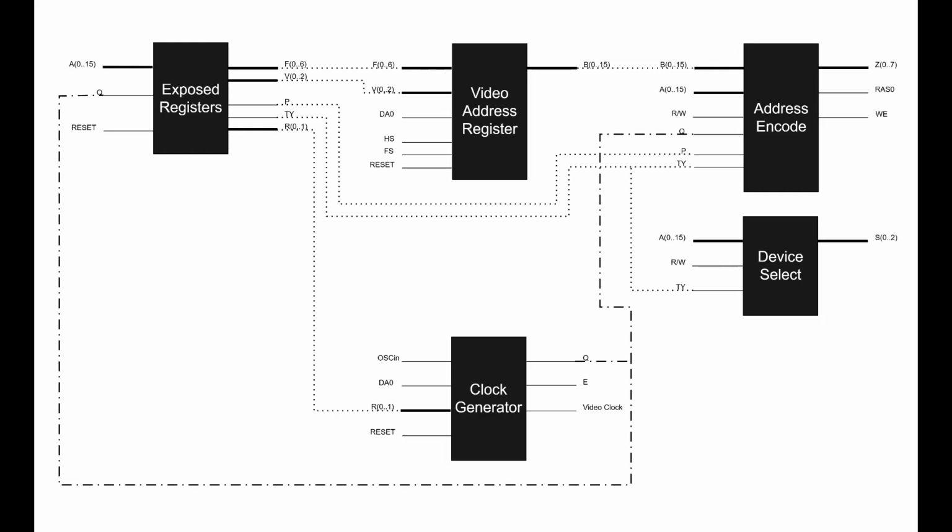There is one signal missing from most of the components in the diagram, the main clock. The original SAM datasheet doesn't explicitly state when data is latched, although it can be inferred. There are a number of delayed triggers that suggest the answer is that there isn't a single synchronized clock. My version, however, uses the master clock to synchronize transitions. This has a slight side effect.